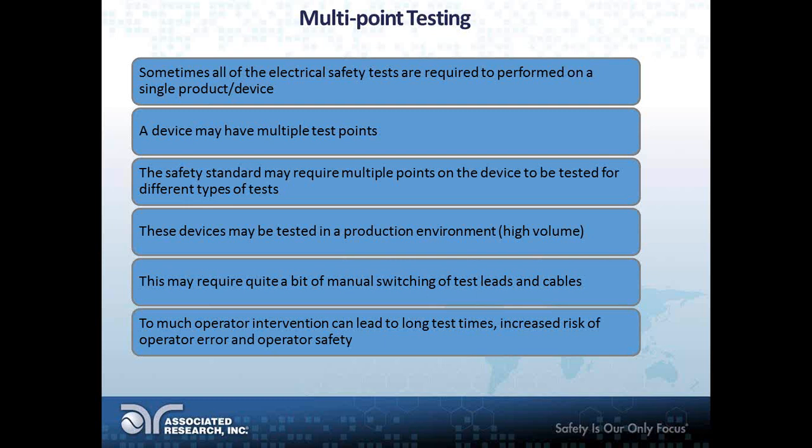The nature of multi-point testing is that it can drastically increase setup time, contribute to operator errors, and reduce production efficiency. And as we know, until recently, test operators were forced to change connections and rewire test leads in between each test. All the negative aspects of multi-point testing can be eliminated by using a scanning matrix, which we are going to talk about shortly.